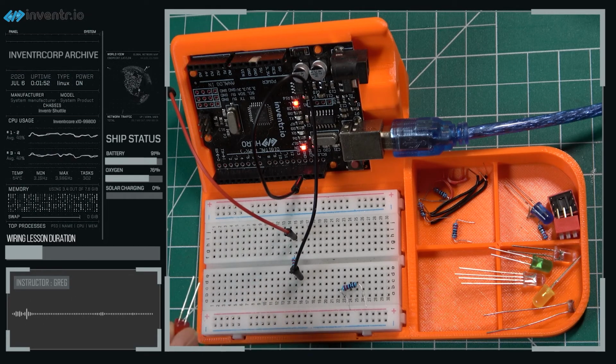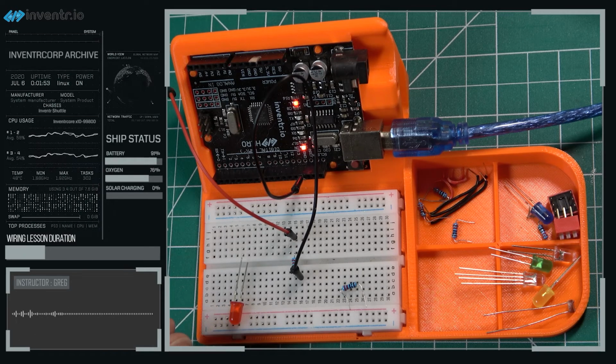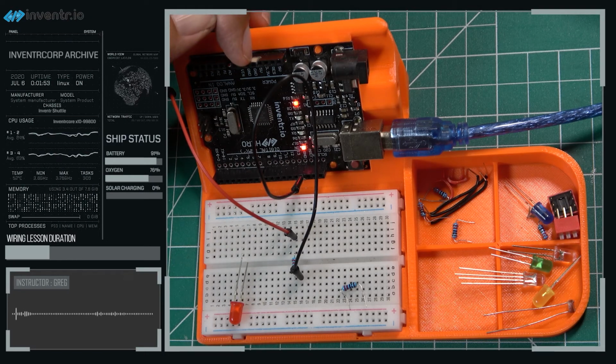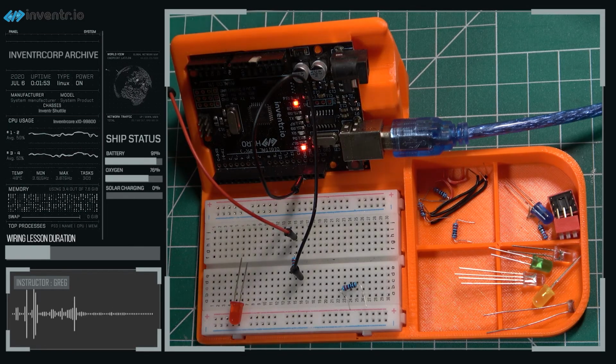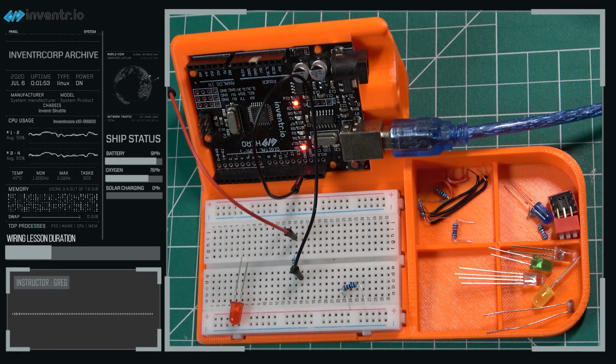That's what this component is, right here. To do this, we need to construct a complete electrical circuit that sends the right amount of current in the correct direction through this LED. The Hero is able to provide a voltage of plus 5 volts, and it also provides a 0 volts or ground level on the corresponding labeled pins. You'll see that there's a 5 volt pin up here in the upper row on the Hero, and there's also a ground pin down here below on the Hero.